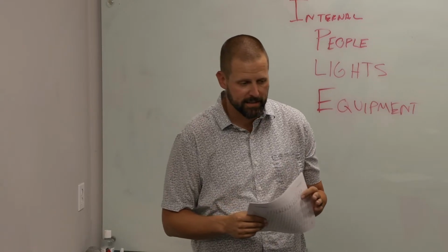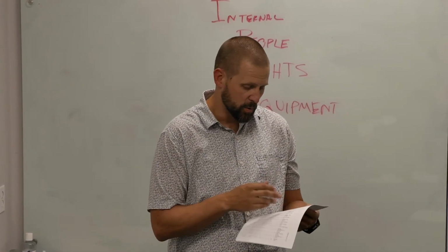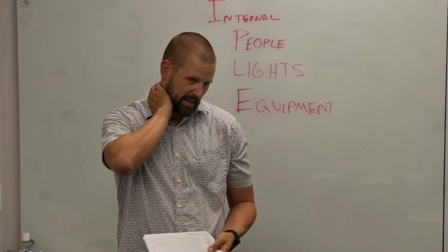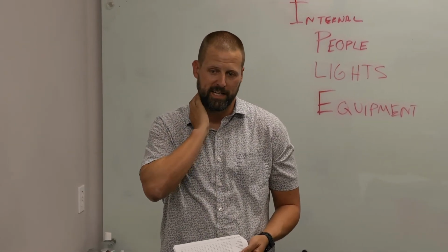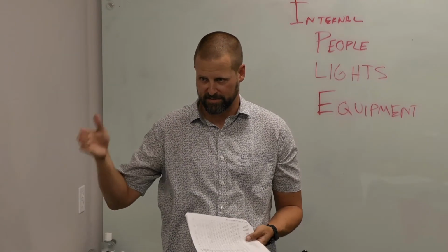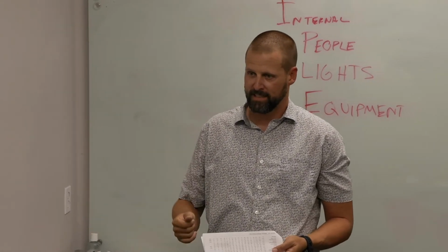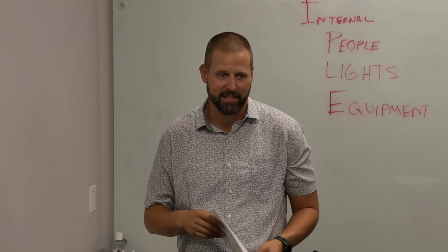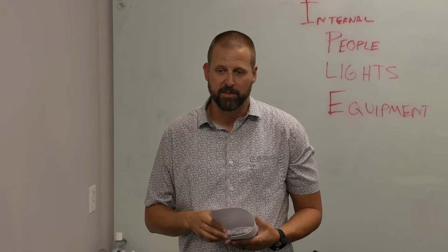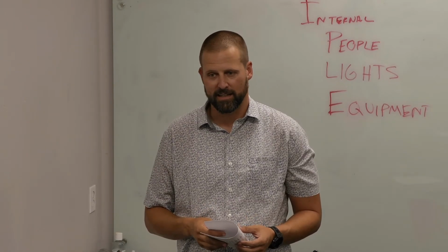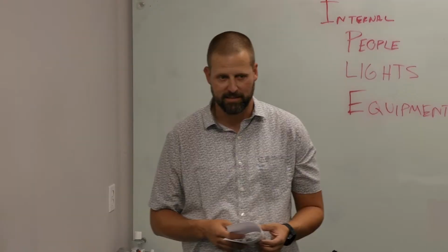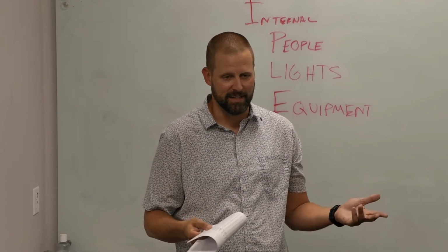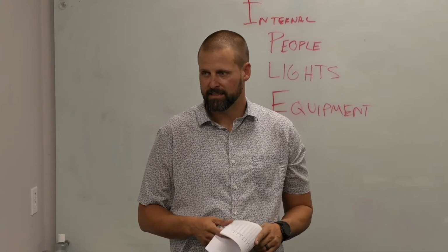The peak cooling temperature may not correspond with the highest enthalpy. So out at Eisenhower, while we have 117 degree days at 74 wet bulb and higher, and Ron and Sam and David will tell you how hot it is out there right now, sometimes the worst days are when it's raining at 100 degrees and we've got 100 degrees outside and like a 79 degree wet bulb.